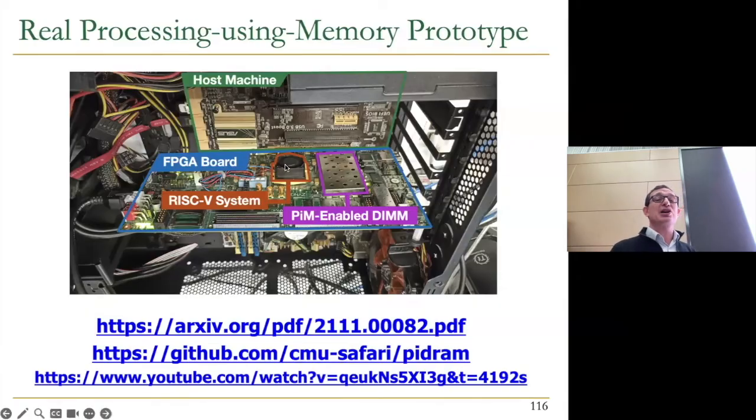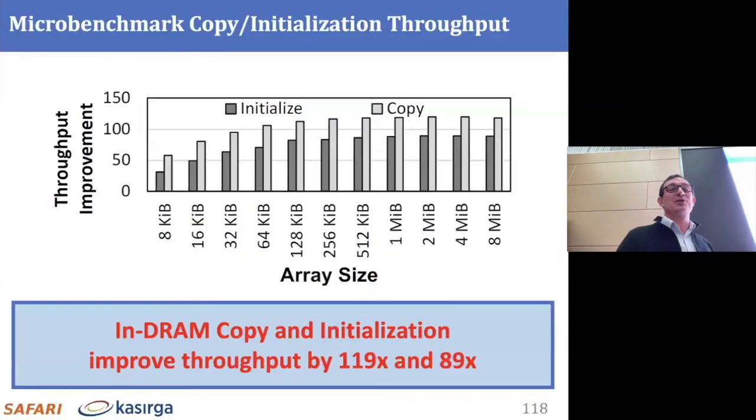That page copy operation gets shipped to the memory controller inside the RISC-V processor. The memory controller violates the timing parameters between two activations to the subarray and copies the source page to the destination page inside the memory. So you can do it in an existing system today. You can download the source code, etc. You can use it. It's a lot of system engineering, and we'd be happy to support it.